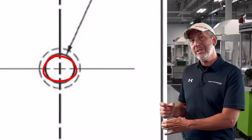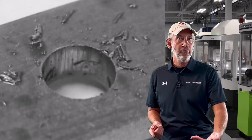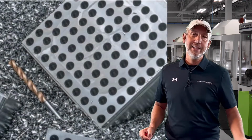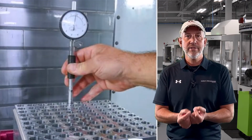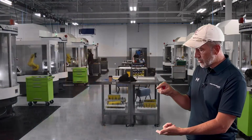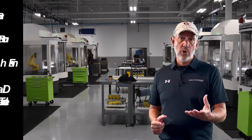So how round is that hole? Also, what does the finish look like on that hole? Finish is very critical. This is where we're getting into high performance. We need to have a nice finish on the hole. And last but not least, because there's a lot of things with hole quality, last is what is the diameter tolerance on that hole, and how well can we hold all those dimensions, straightness, roundness, finish, with that diameter, that hole size for a long time.